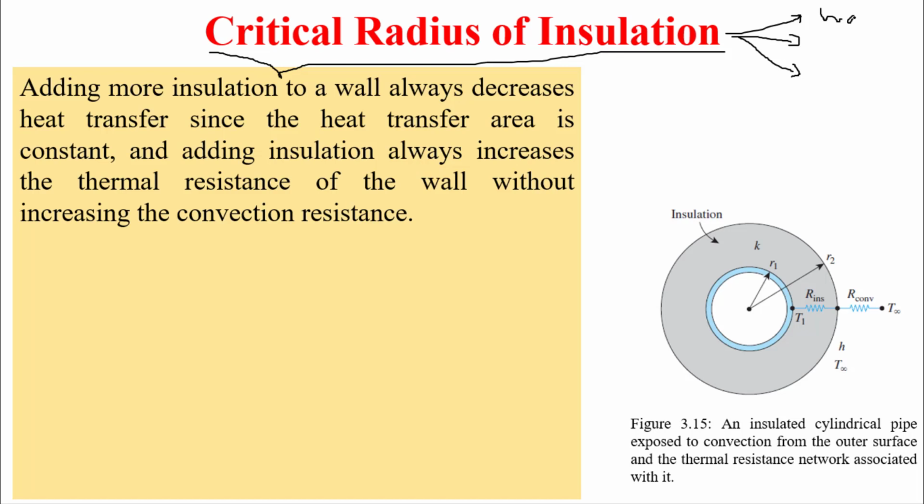Either we have a wall, or we have a cylinder, or we have a sphere. So this is the first scenario, for a wall. What is the result of adding more insulation to the first geometry, which is a wall? Always decreases heat transfer.